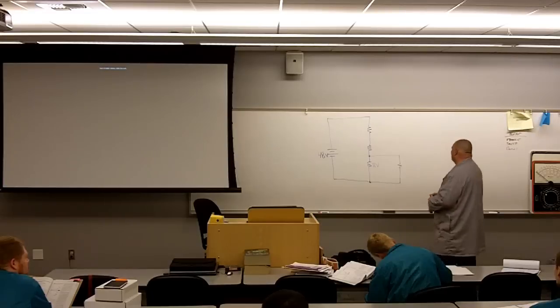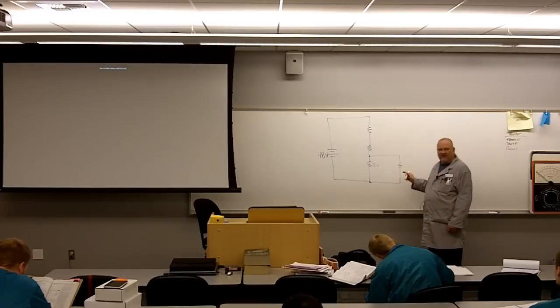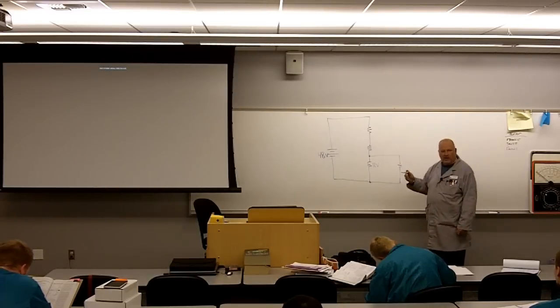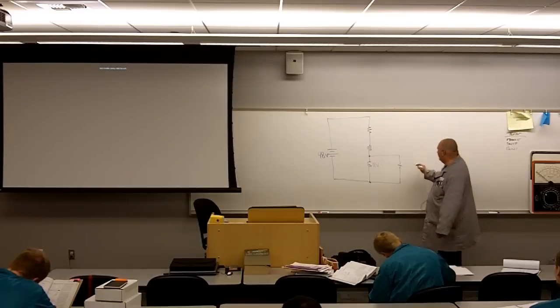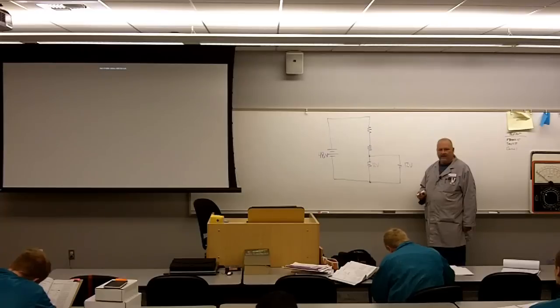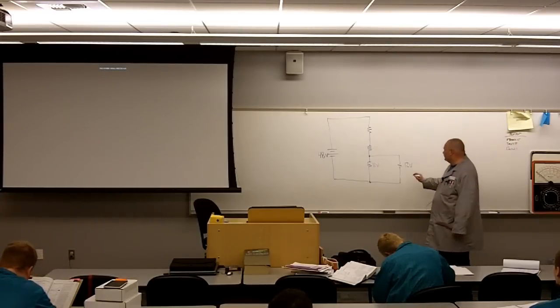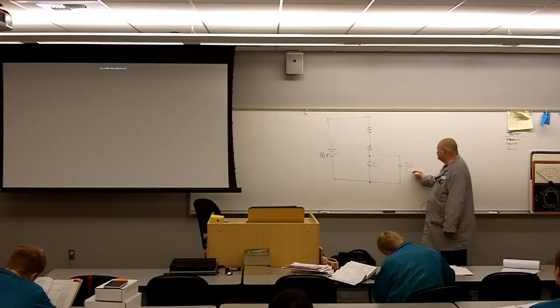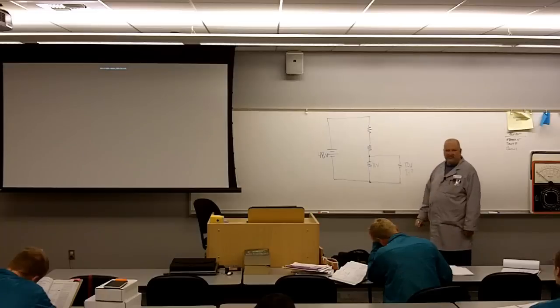So, we know that this is 12 volts because the manufacturer said this is a 12 volt CB radio. You could plug it in your cigarette lighter, you could wire it into your car, and you too could be breaker 19. Make sense? So we know the voltage is going to be 12 volts. The other piece of information that is critical for us is how much current is required by the CB radio to operate properly.